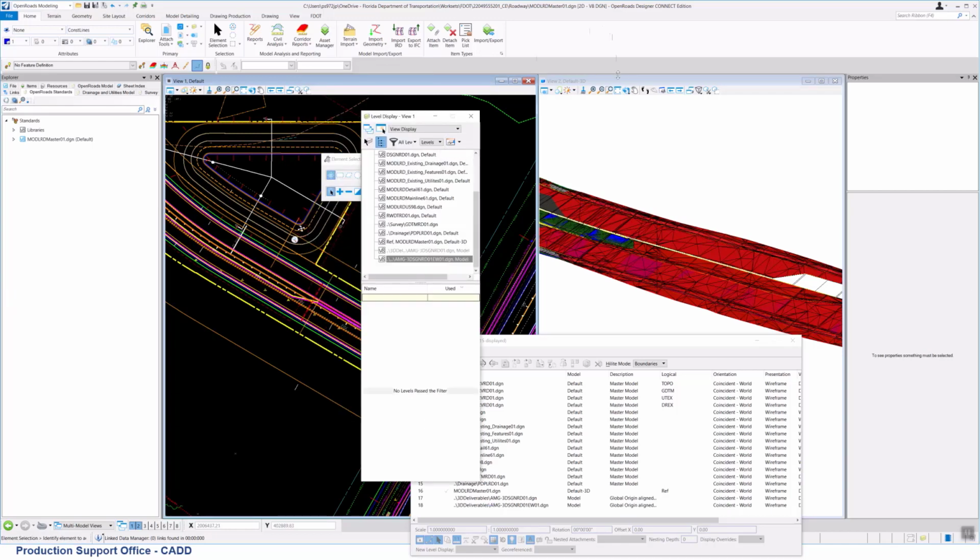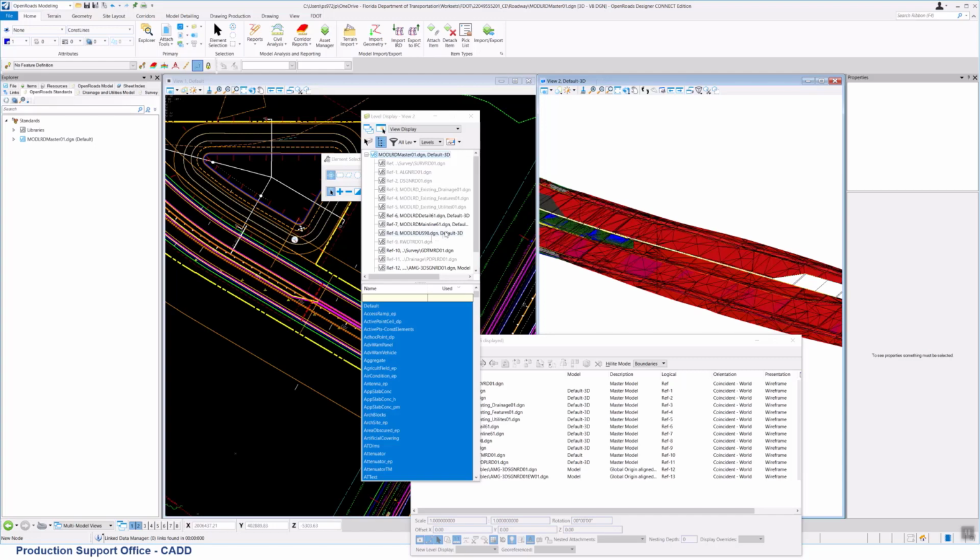That looks better. In my 3D view, I want to turn off cut and fill volume, so I come over here to, I'll just do all the model files. If in doubt, that's the easiest solution. Then I'm going to turn off cut_PM and fill_PM, just to turn off those two levels.